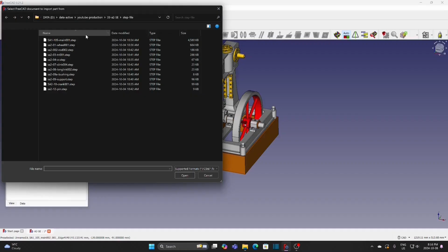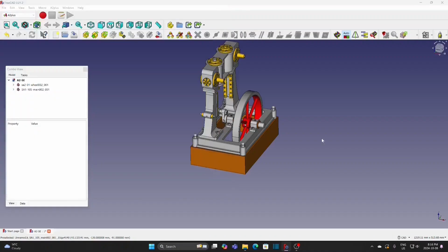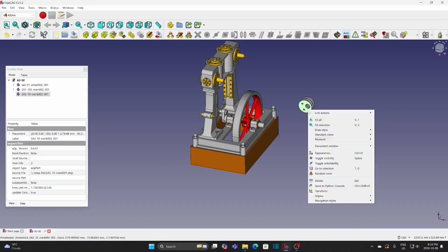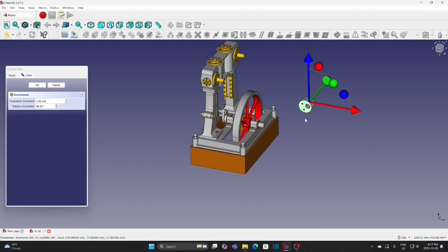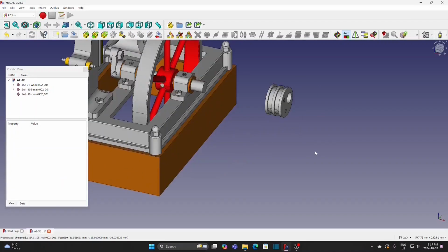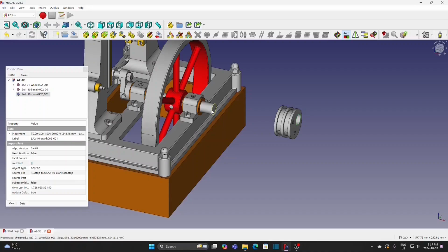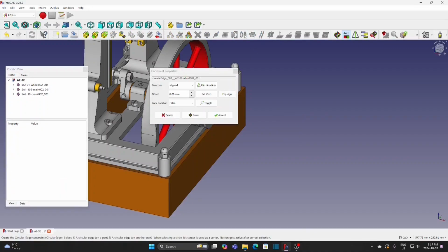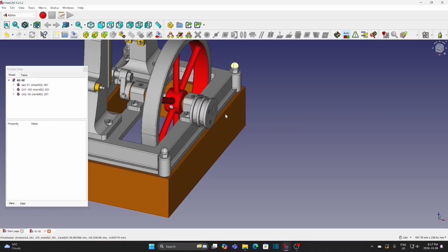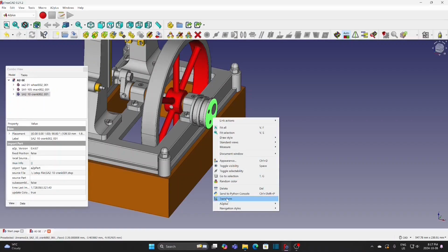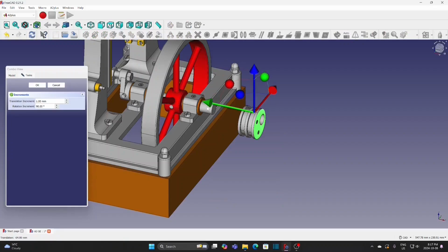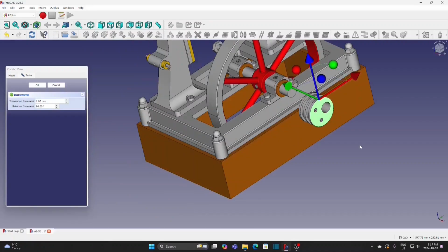Add the crane. Rotate it by 90 degrees. Select the circular edge at the crane and the shaft. Add circular edge constraint. Always hold the Ctrl key when select the second circular edge or constraint. Although the crane fits into the shaft, rotating the shaft will not rotate the crane. So we need to lock the crane at the shaft.